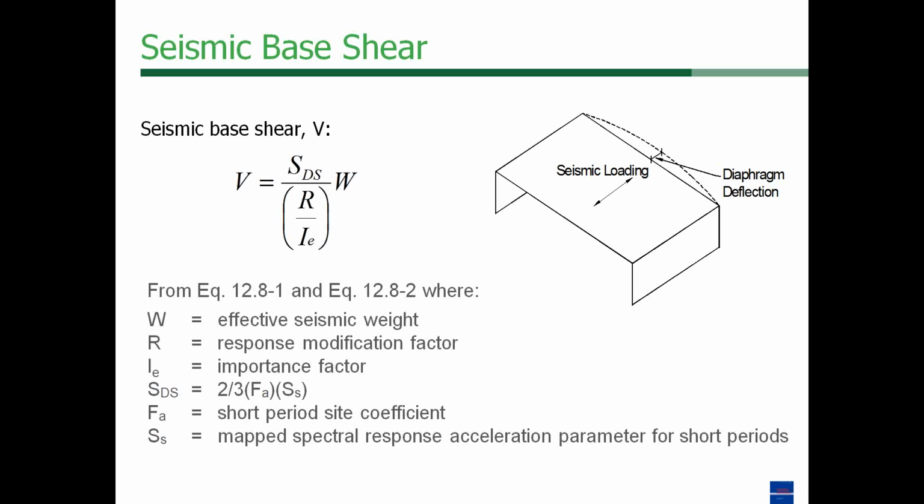Now there are other provisions of ASCE 7 that allow lesser shear for the structure as you get higher periods, but in general this equation typically governs, and there's not much relief that you can gain by trying to take advantage of longer periods for wood structures.